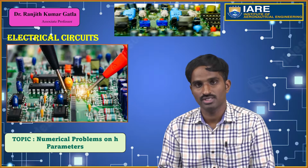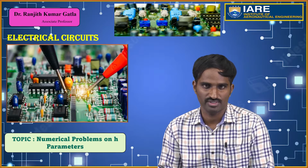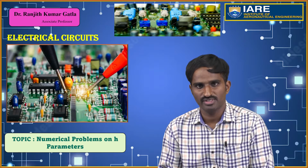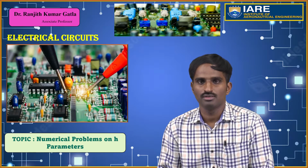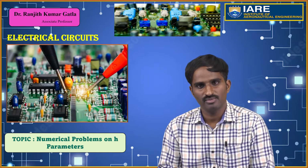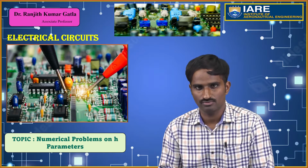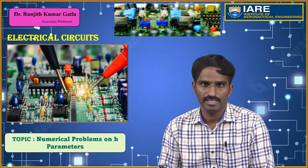That's why those are also called short circuit parameters. But unlike the Z parameters and Y parameters, in the hybrid parameters, the secondary side we make short circuit and the primary side we make open circuit to find the H parameters.